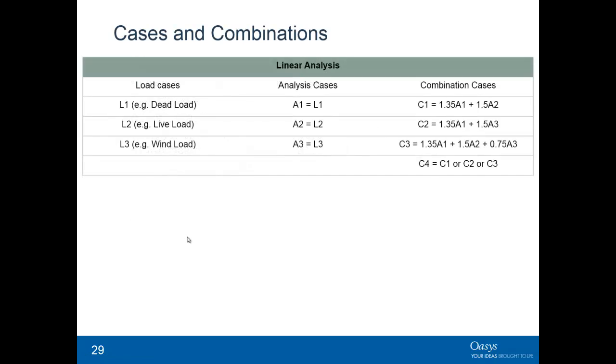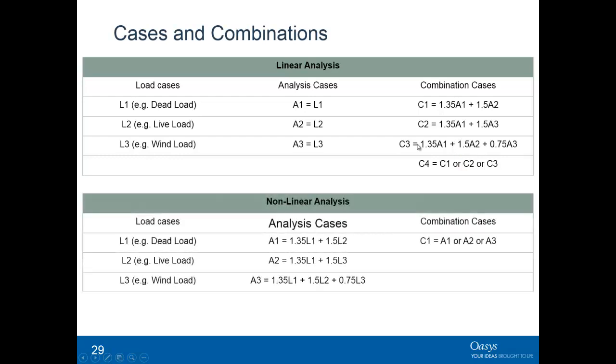But it's another way. Let's look at the table view. So for linear analysis, you've got, let's say, dead load and load case 1. GSA will create analysis case 1, and then you can do the numerical calculations, combinations, including envelope. Whereas with the non-linear analysis, the combinations must be set up within the analysis task itself, because load paths can change because the equilibrium is based on the deformed geometry.